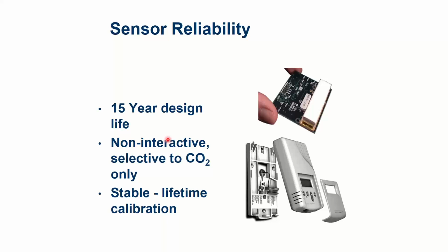and then let it roll. The problem with that is there's a button on there, and people that aren't comfortable in the space for temperature or humidity reasons start messing around with stuff. Same thing with the paper clip or the guy on the ladder I was talking about. They end up pulling the sensor off the wall. They see a button, assume it's the main master reset button, press it, but there's no can of gas flowing, and they just jacked up the whole CO2 reading. So most of the manufacturers of commercial grade sensors have removed the calibration button on there. And if you get one that goes out of calibration in the warranty time, they just give you a new one if you happen to have that scenario.